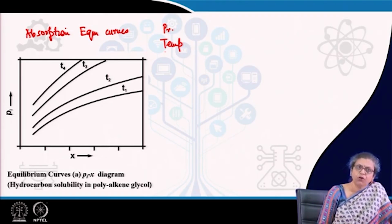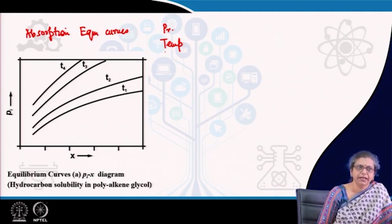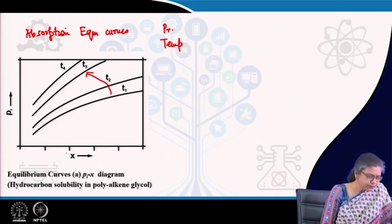So, most absorption cases are accompanied by release of heat, or in other words they are exothermic. Therefore, for most cases we find that as we increase the temperature, the curve becomes more and more steep and the solubility of the gas decreases.